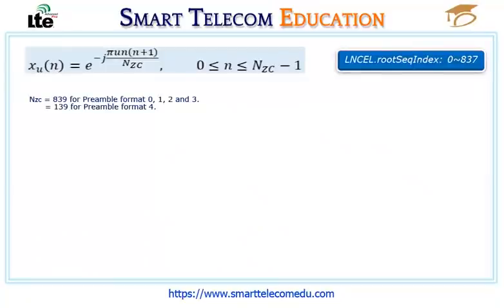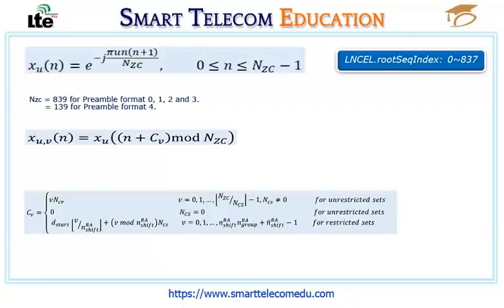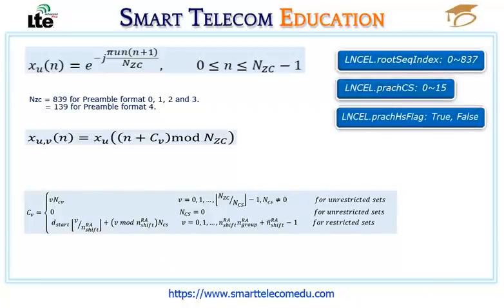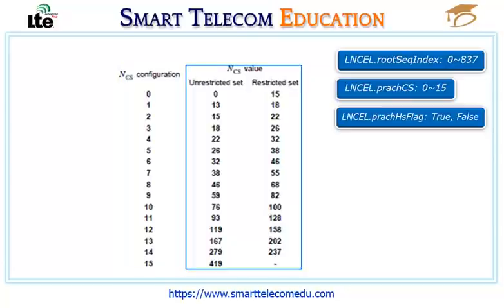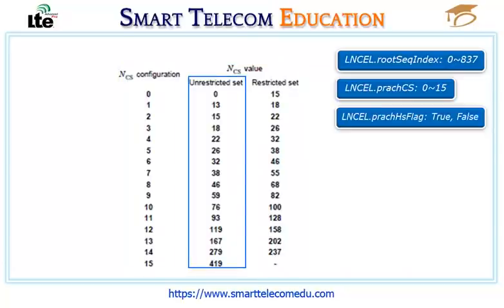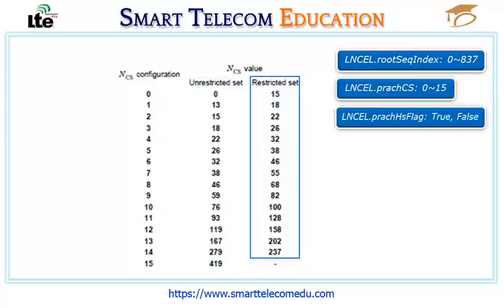Now, the generation of 64 preambles from a single base sequence is given by a cyclic shift defined by the PRACH CS and PRACH high-speed flag parameters. The mapping between PRACH CS and the cyclic shift NCS is determined by the following table. The first column is the PRACH CS config parameter and the second column is the NCS value. The unrestricted set is for high-speed flag equals to false and the restricted set for high-speed flag equals to true.